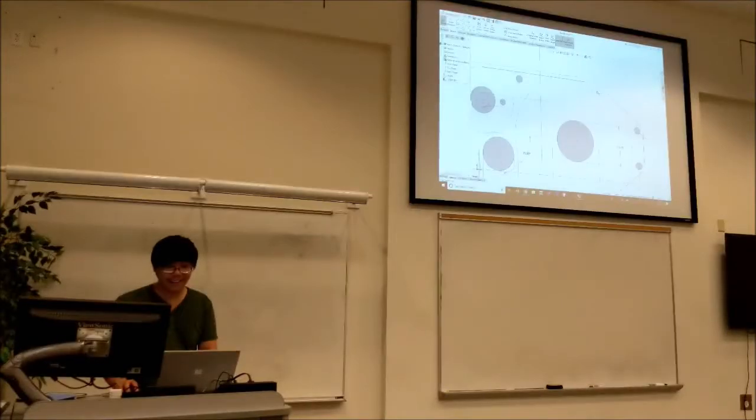And then here, I'm doing it kind of sketchily, but what I'm doing is just closing off this corner here. And I'm doing just 3/8 just to keep the radius on the corners constant. And then we can extend this line to hit this circle. And then we can do another one from here to here.